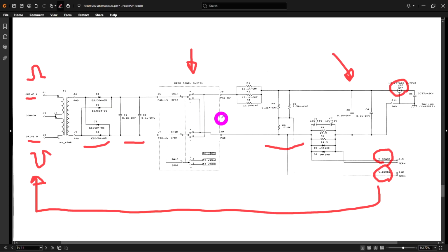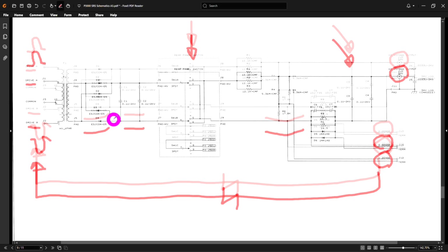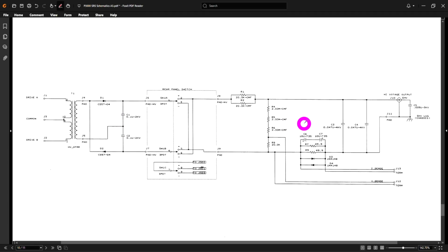And as a result, this is going to operate in a continuous loop. And if you break this loop, you're going to get some wildly changing voltages at the output side of this circuit. Now, in order to reuse this front end and all the other circuitry that's inside of this unit, they can just change the way this rectification works in order to achieve higher voltages. And that's exactly what they do for the next one up. So this is the one that goes to twice the voltage, 2500 volts.